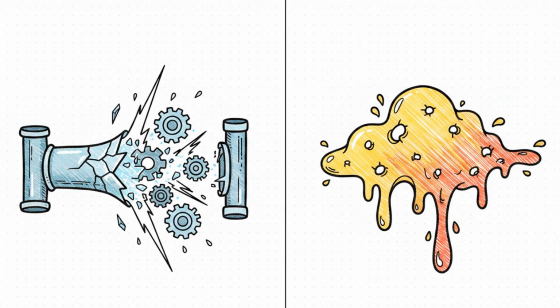If our 3-zone extruder is too cold, the machine physically breaks down. The material just fails to flow, you get severe pressure spikes, and that can actually tear apart the drive mechanics. And trust me, nobody wants to explain a shattered gearbox to their boss. On the flip side, if it's too hot, the plastic is structurally ruined. Thermal degradation causes microscopic voids that completely wipe out the material's mechanical strength.